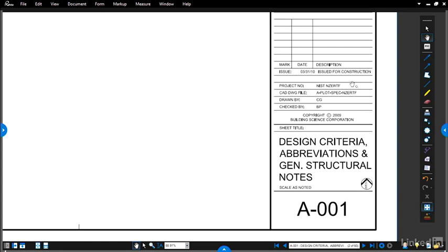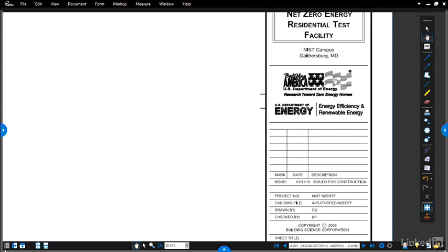This information generally helps the designer find their project file name, maybe their digital file name, so they can pull it up later. But these two pieces of information here are the drawn by and checked by information. You have initials or names that give us some indication as to the detailer that actually drew this page and maybe the detailer that checked it. So that gives us two names that we can associate with this page or this set of drawings.